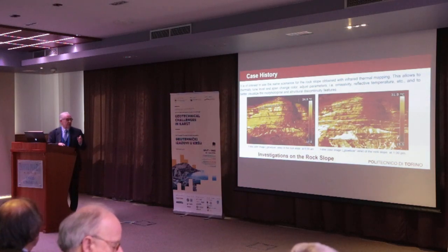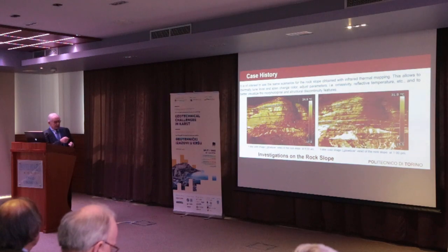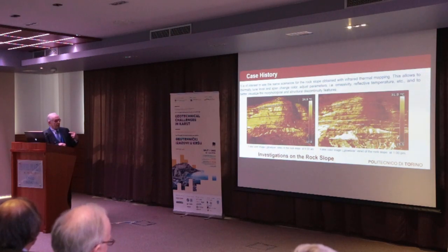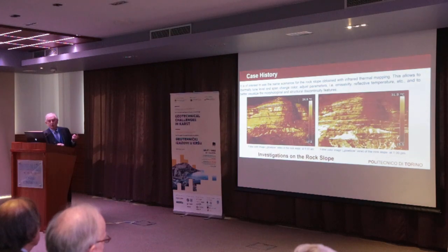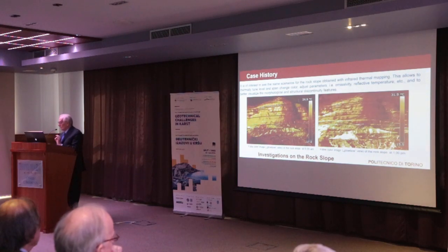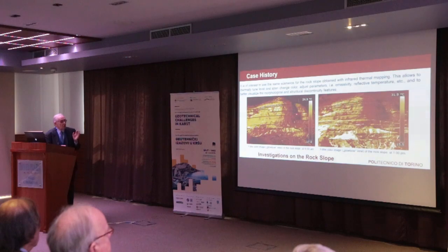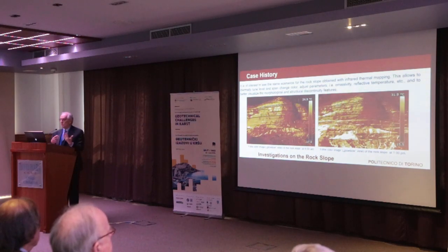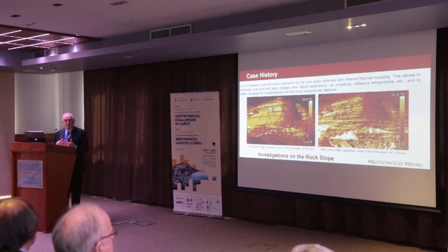infrared thermal mapping. You can see two pictures here. This picture was taken early in the morning, 8 o'clock. This picture was taken in the afternoon. Of course, if you go careful and you see in detail all these features which are known well in XYZ coordinate, and you look at the different colors, you associate humidity, you associate structural features, you get into the point cloud. The infrared thermal mapping can allow you to have a good understanding of the three-dimensional features.